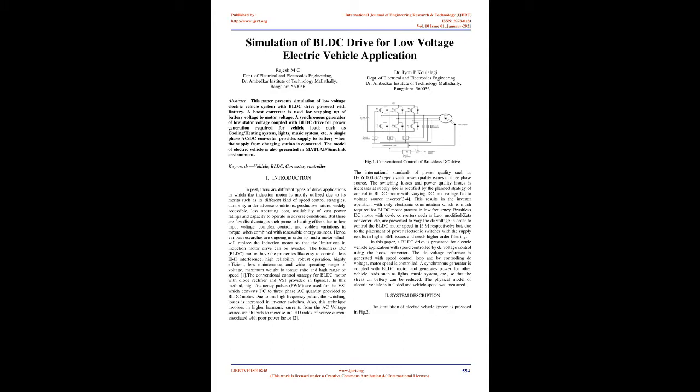Hence various researches are ongoing in order to find a motor which will replace the induction motor so that the limitations in induction motor drive can be avoided. The brushless DC, BLDC, motors have properties like easy to control, less EMI, high reliability, robust operation, high efficiency, less maintenance, wide operating range of voltage, maximum torque to weight ratio and high range of speed.